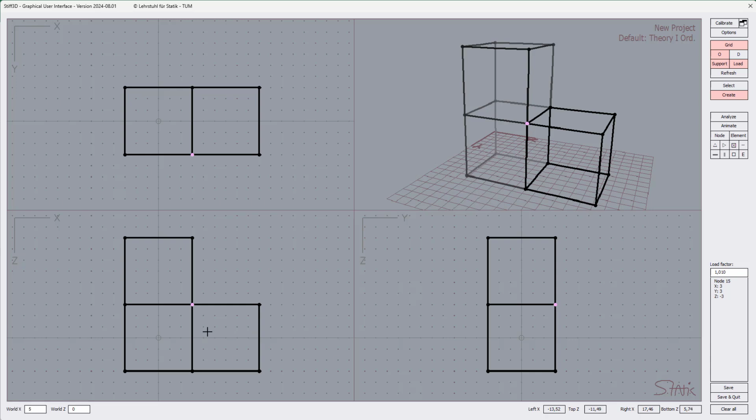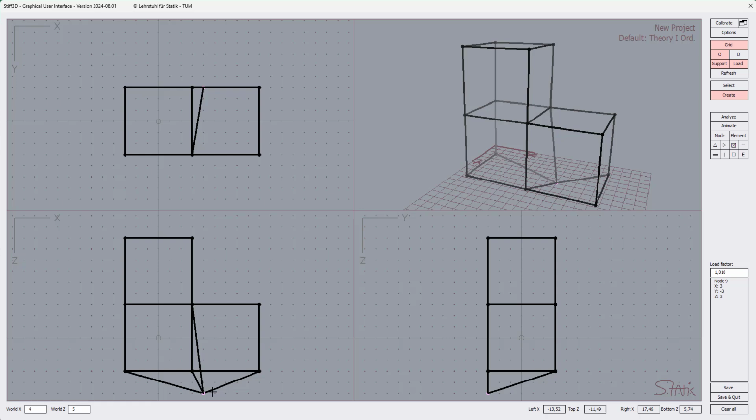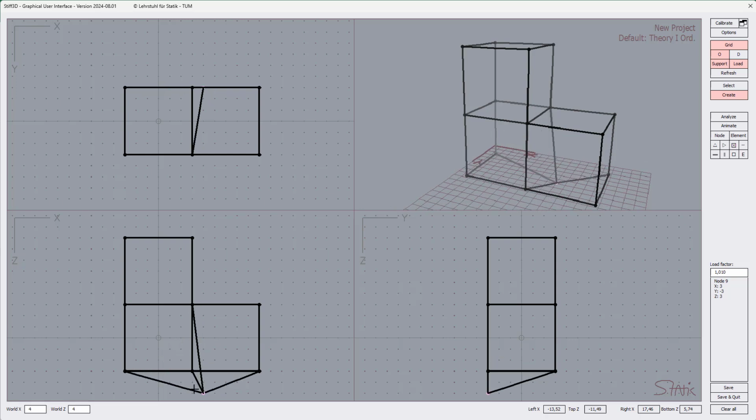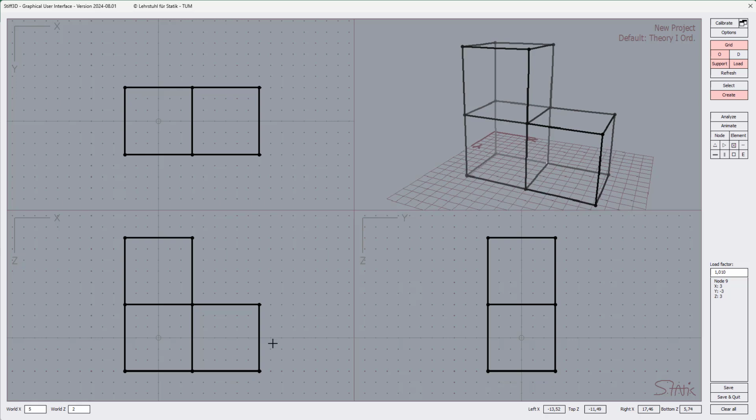And if everything has been merged and we are moving that node, you see that everything is just moving as it should be, telling us, yeah, indeed, there's only one node left here. The same story for all the other nodes which should be merged. So as we move that, you see there is only one element attached to that, and it just seems indeed only one node.